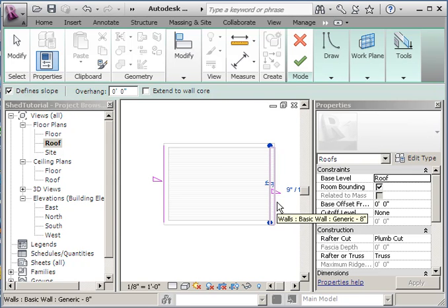It says you can create a roof boundary by sketching the edges, but an easier method follows. In the options toolbar, enter 1 foot for our overhang. So that's 1 foot right there of overhang. And then it says select the 2 opposite walls of the building.